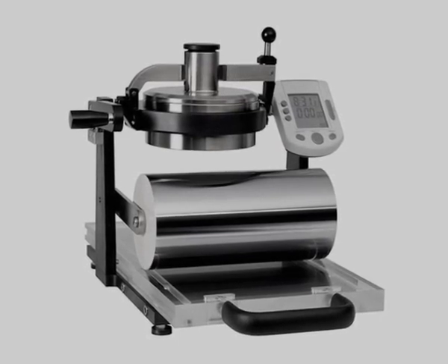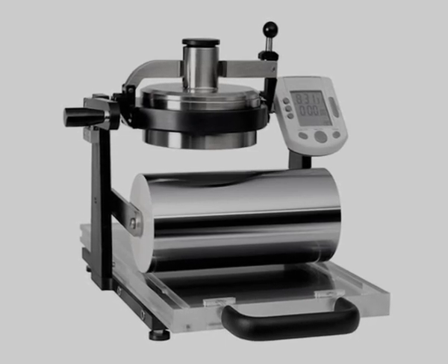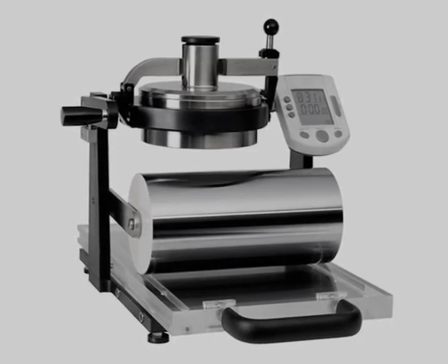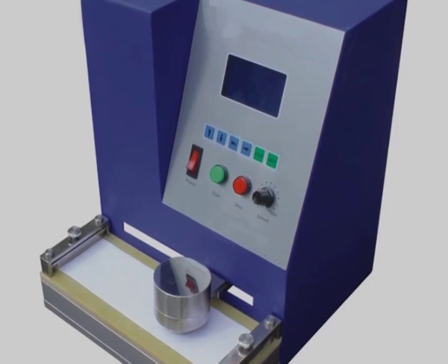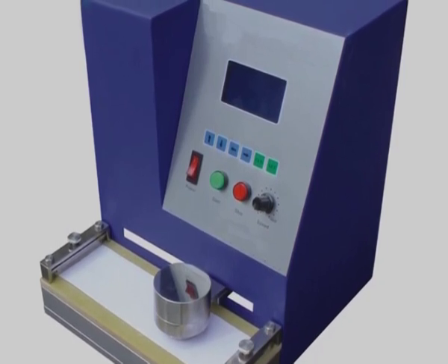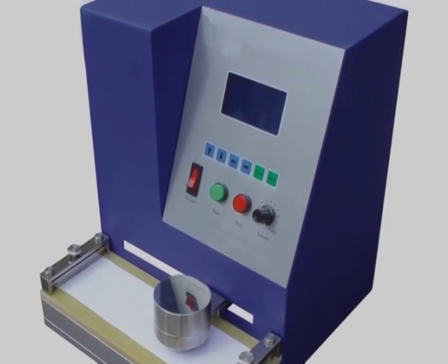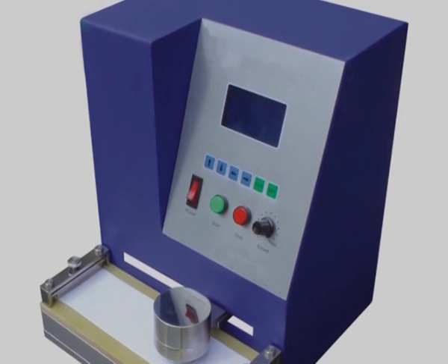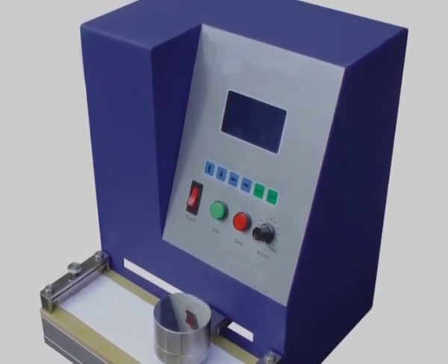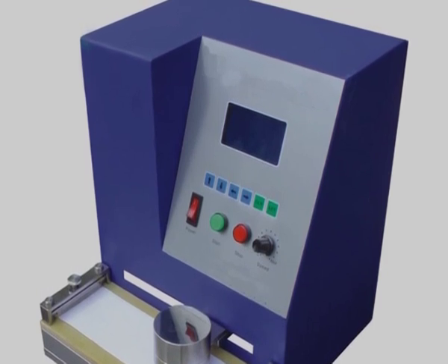It is determined by weighing before and after exposure to the water and usually quoted in gram per meter square. Number 17. Rub resistance. This is the resistance of a printed test piece to withstand rubbing against either another similar printed test piece or against a plain test specimen. The objective is to see that the ink print has cured and will not scrub or smear in service.